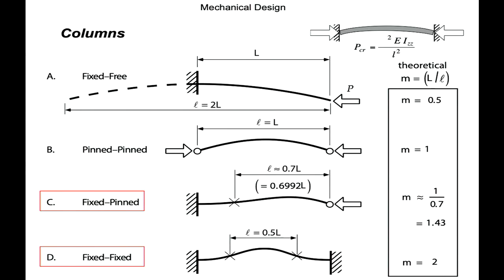Just as an aside, what's great about the stuff I teach you is you're in the lecture and you forget this stuff and you're allowed to take a ruler in. All you've got to do is think, okay, the top one, I've got a pin joint; top left-hand corner, fixed-free corresponds to fixed end at one side, free at the other, and we get that kind of effect.